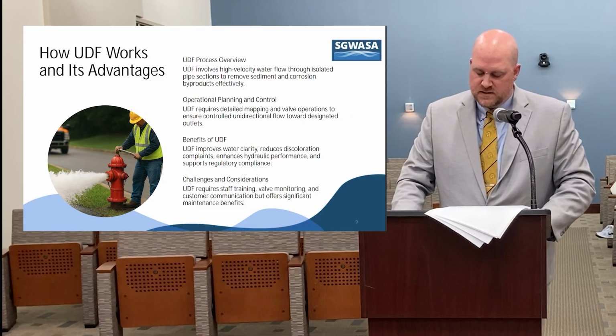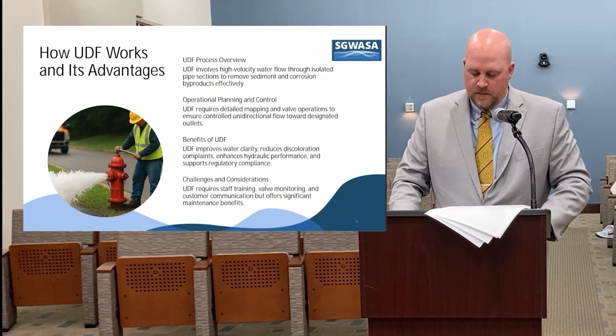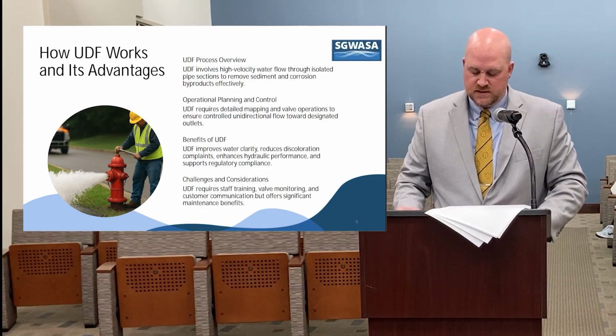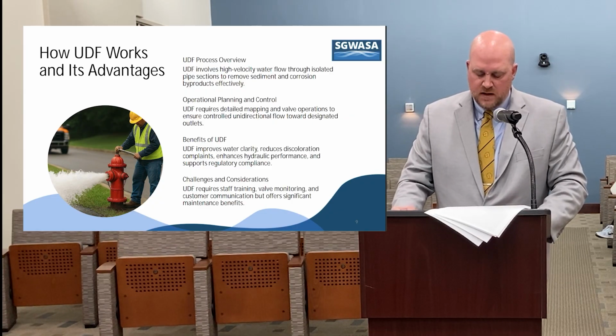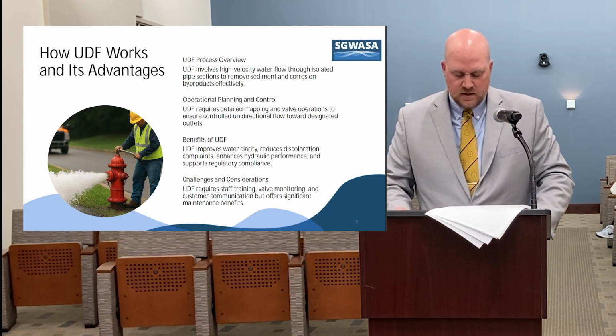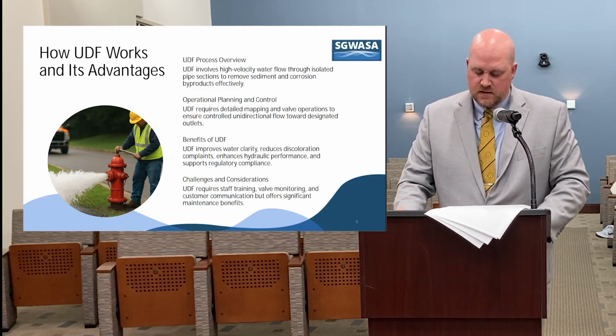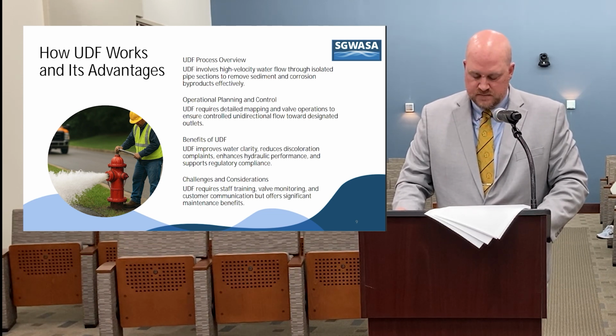Unidirectional flushing requires detailed mapping and valve operations to ensure controlled unidirectional flow towards designed outlets. The benefits of this unidirectional flushing improves water clarity, reduces discoloration complaints, enhances hydraulic performance, and supports regulatory compliance.